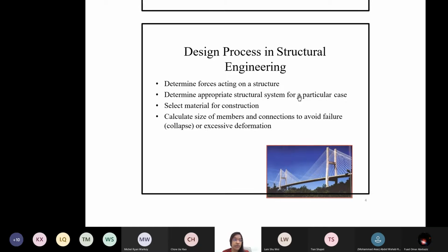Like that, when a structure is given to you, you should know the combination of loading. Later we'll see types of load. With that, you should know which combination, whether for a 2-story building, just live load and dead load are enough. When you go to a tower building, you must include wind load and earthquake load, and for wind load, what type, for seismic load, what type. All these things are to be analyzed before you go for design.